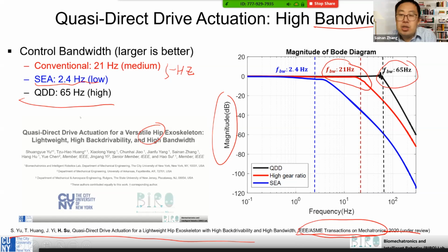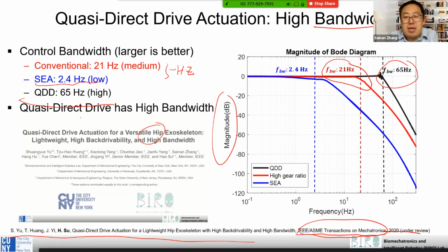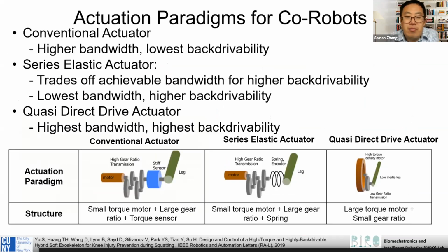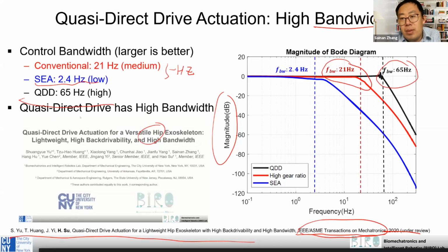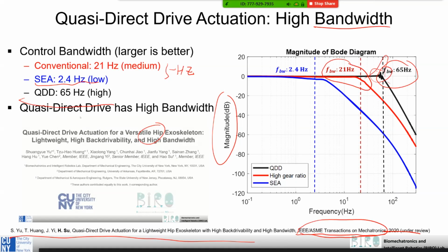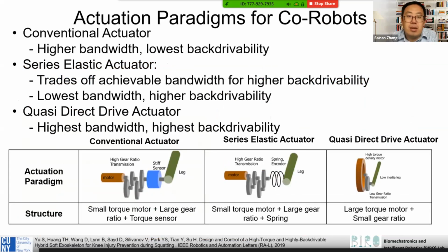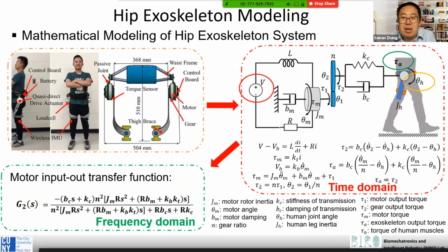Yeah, that's kind of normal. I think you can play with the PID control, and also in reality, when you get close to a resonance frequency, if you don't tune it very well, you can get a very noisy plot. I will show you that in the next few slides. So it's not smooth even in your simulation.